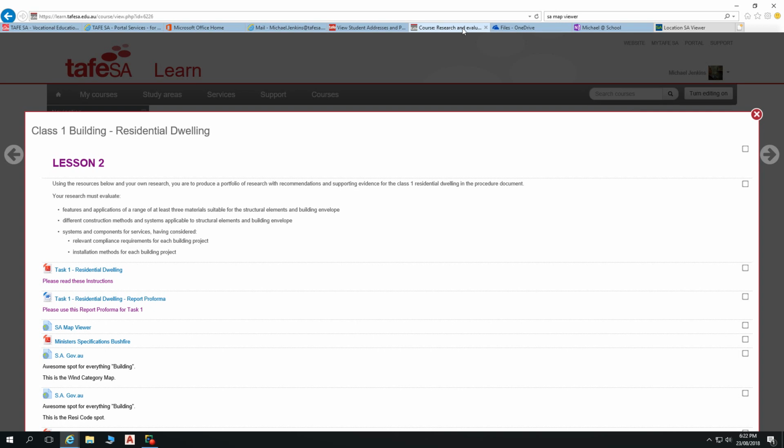Other maintenance aspects in relation to housing. I think the most important maintenance aspect in regards to housing is ensuring that gutters, downpipes, etc. are not leaking and not cracked at the ground level. That's probably the biggest issue for housing, to ensure that there's no moisture where you don't want moisture.